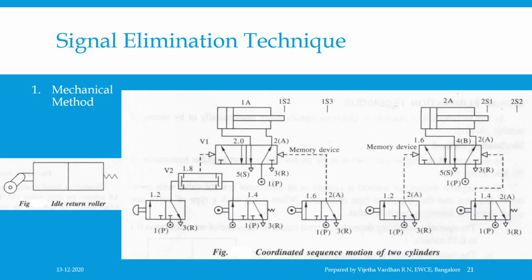Signal overlapping can be eliminated by use of lever valves with idle return as limit switches. These valves are actuated in one direction of movement only by the piston rod and are configured in such a way that the actuation is triggered just shortly before reaching the respective initial end position.